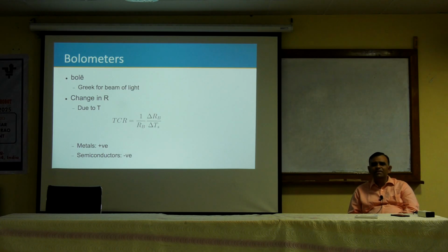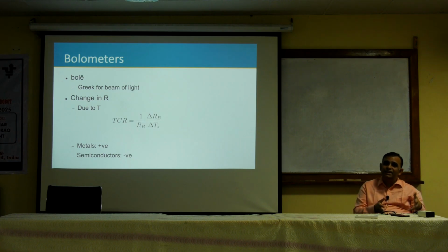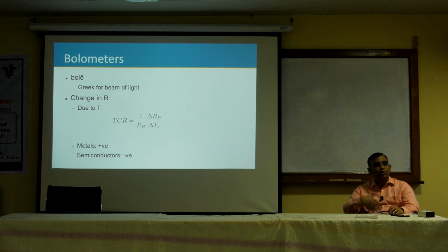But then metal resistance should also fall. But we know standard resistors, their resistance increases with temperature. So, the bottom line is that the more temperature you have, the more thermally generated electron-hole pairs are generated. In semiconductors, you have a larger number of charge carriers available to carry current. If more charge carriers come in, your native resistance falls.